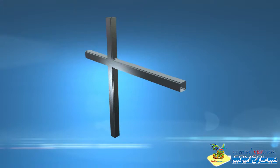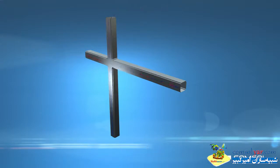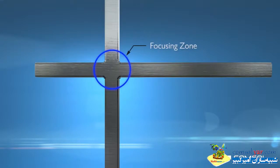This particular video will describe the focusing stage, in which a fluid containing the ionic species flows from left to right in the horizontal channel, driven by a pressure gradient. Pressure-driven flows also inject buffer solution into the horizontal channel from both the upper and lower vertical channels, leading to a focused concentration profile at the junction.